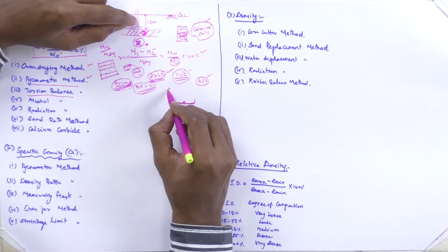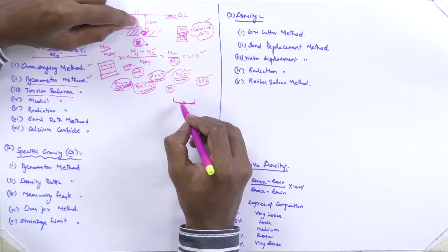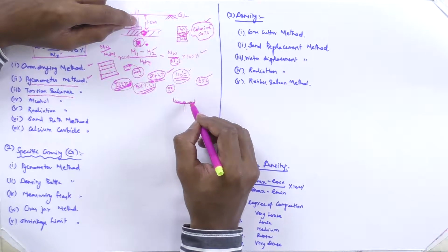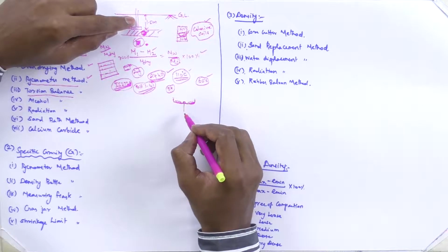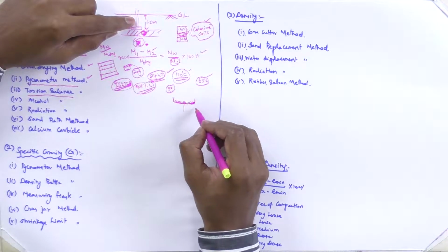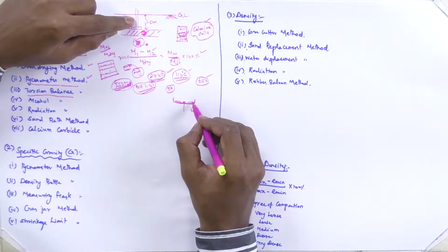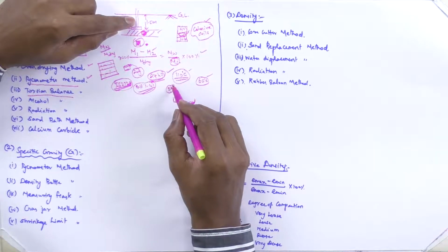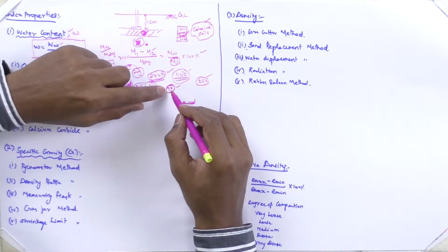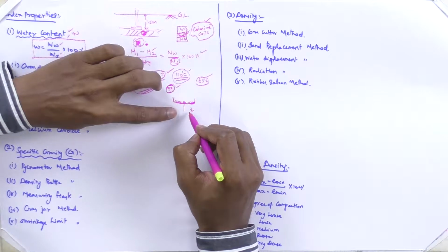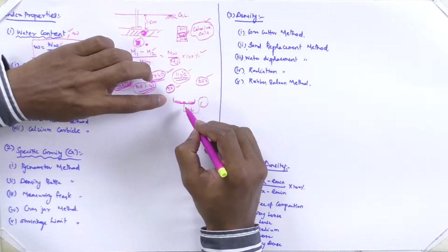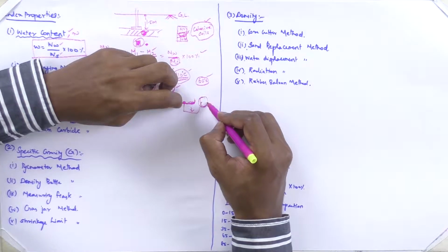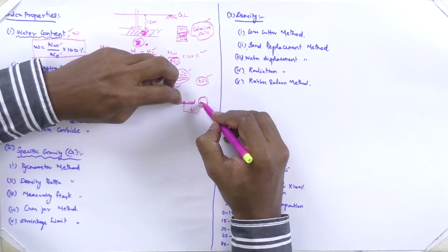You take a little 5 to 10 grams of soil and pour it over the surface of the plate, and the needle goes down when you add soil. There is no need of weighing the 5 grams beforehand. It is mechanically attached to a graduated circle that shows moisture content.